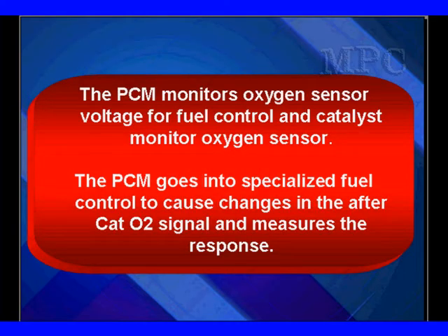The PCM monitors oxygen sensor voltage for fuel control and catalyst monitor sensor. At the same time when it does this test, the PCM goes into specialized fuel control to cause changes in the after-cat O2 signal and measures the response.